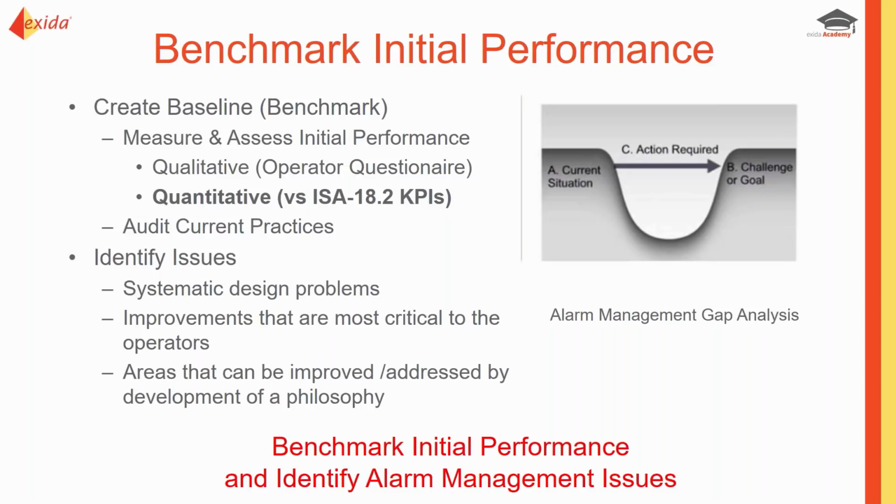It also includes a qualitative assessment of performance, such as you might have in an operator questionnaire, and then also some auditing of the actual work practices that you use for alarm management. And as I mentioned, this benchmark establishes your initial performance threshold, as well as identifies your systematic design problems that you want to get fixed through your alarm management program and in your alarm philosophy document.